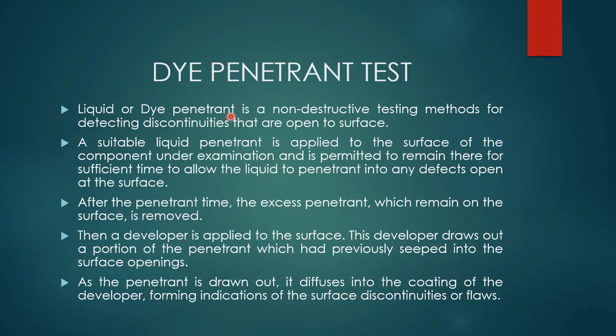Now next is dye penetrant test. This is one of the most important and mostly used tests in industry, which is basically used for checking surface cracks. So what is done in this particular test? You can see liquid penetrant is applied to the surface of the component and is permitted to remain there for sufficient time to allow the liquid to penetrate into any defects.